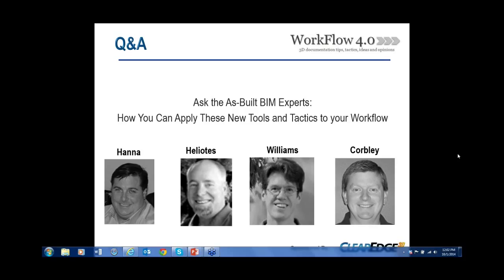Okay. Chris, do you have anything to add on that one? Yeah, it kind of depends on what the end result is. Obviously, I'm not doing targetless registration on everything, only in applicable situations. If I am doing it targetlessly, generally what I'll do is collect a set of verification points with a total station, and once I've done the targetless registration within Recap, I'll bring it into a program like Cyclone, and I will QC against the tied information. Okay. All right. Good. And Kevin, here's an interesting question.